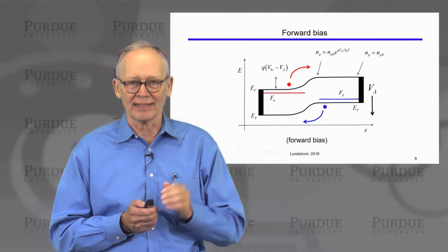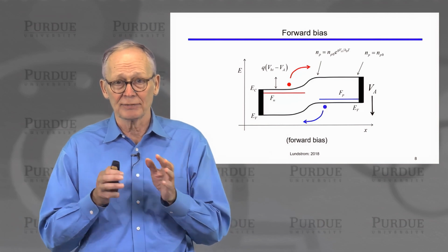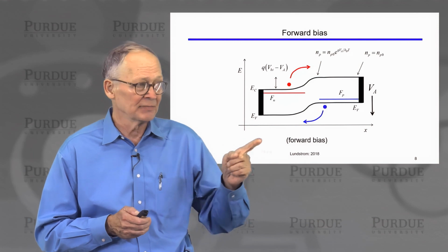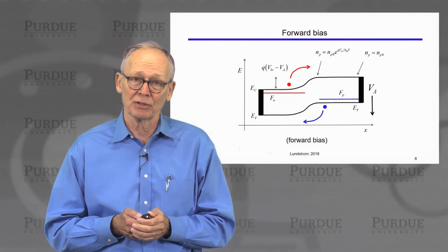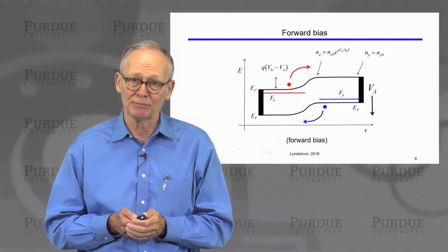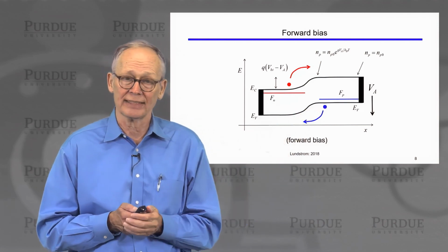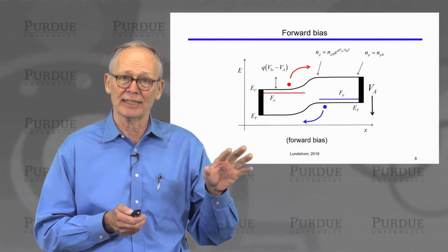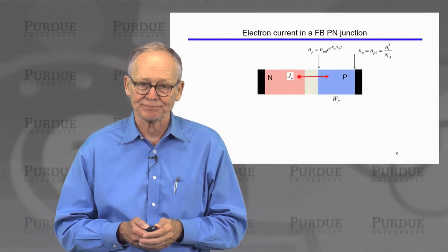Remember, these are always electron energy band diagrams that we are drawing. Electron energy versus position. Hole energy increase is going down. So this is an energy barrier for holes. The energy barrier for holes has also been lowered by the forward bias. So we're going to inject holes onto the n side. We'll have increased exponentially the concentration of minority carrier holes on the n side.